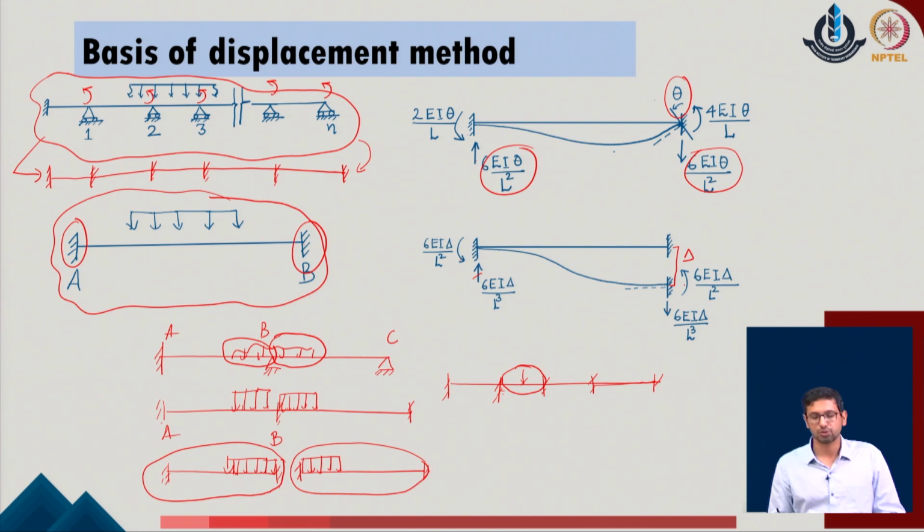In most situations, many times people have doubts with respect to the directions. So, what one can easily do, as a given system is trying to undergo deformations like this, is define the possibility of the rotation which the system wants to take up. The reaction which will be generated will be opposite to it. At the same time, we have to have the reaction corresponding to this given axial line. This is the kind of deformed shape which the system is taking, and this is the possible rotation in which the system wants to move.